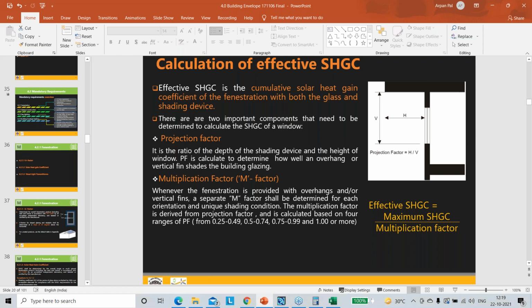window at all, right? Then of course your heating requirement or your cooling requirement will be most effective. But then at the end of the day, you need to see whether you can have any building without any window, right? Until and unless it is a warehouse or something. But then again, you have to see under what categorization warehouses would come, right? So again, ECBC does not prescribe any lower limit for WWR.